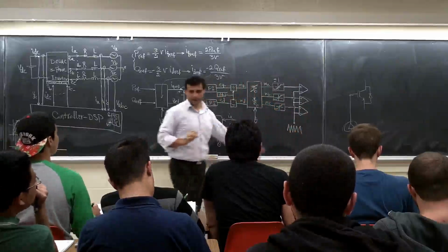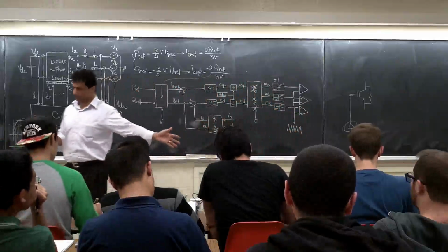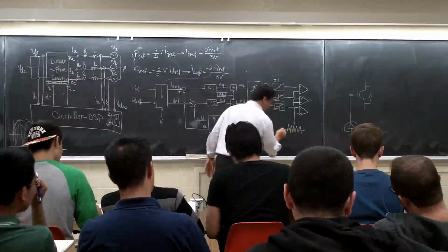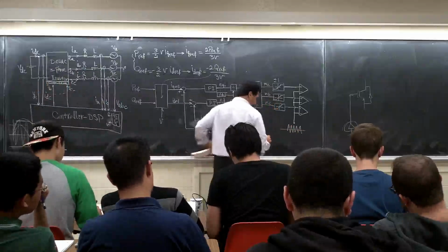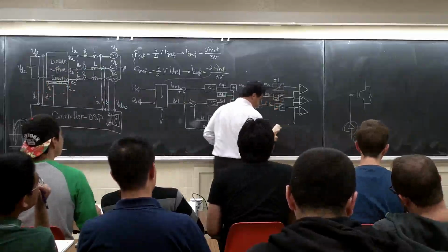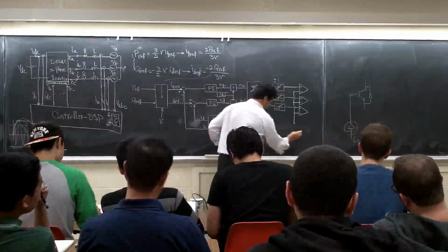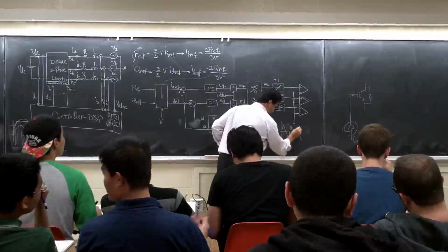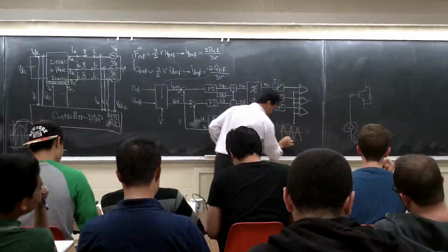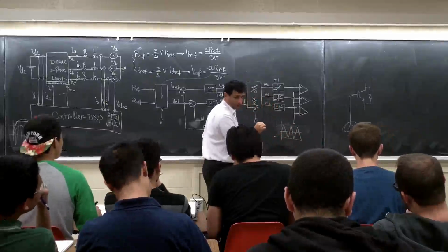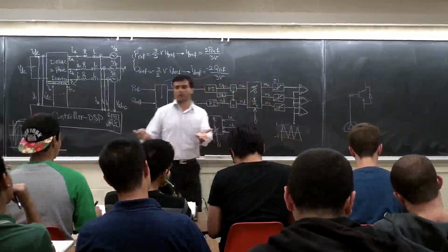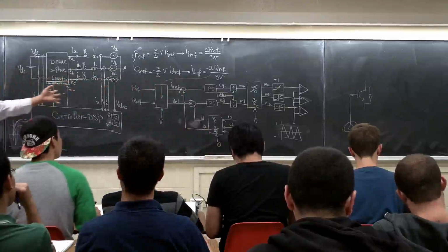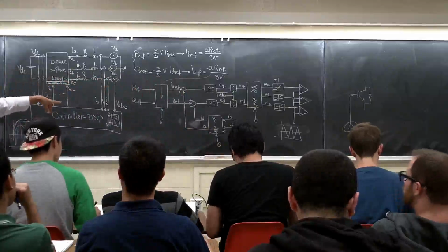VTRI, okay? I'll put a triangular waveform here. Make sure, when you do this one, it's like this. So you're going to set in your simulation: this one is maximum 1, minimum -1, and the frequency is based on whatever we say, 10 kilohertz switching frequency, 5 kilohertz switching frequency. Whatever frequency we say is the switching, you select the frequency for this wave.